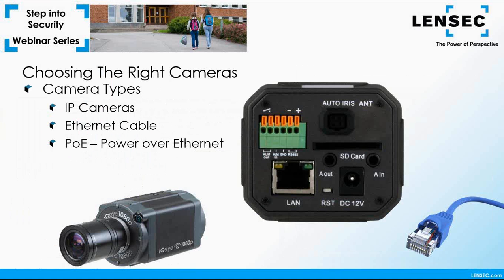Cameras may be within 328 feet of the network switch providing PoE power. Longer distances could be achieved by boosting power with a PoE injector or a mid-span injector. And I've heard of some cases of cameras reaching distances longer than 328 feet, but for the sake of the specification and a conservative approach, always plan to add an injected power when you get longer than that distance.